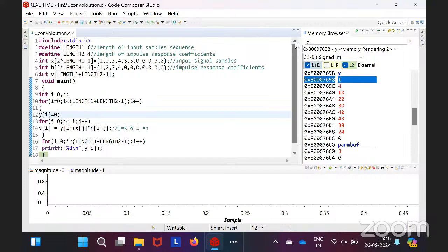Generally in Python you will not be defining types. If you are using FPGA for your design, then you have to select whether you want a fixed point or floating point. Here you will be seeing int means it is 32-bit. Short will be 16-bit. And if I declare these as character, then it will be 8-bit. I can operate on these various word lengths.